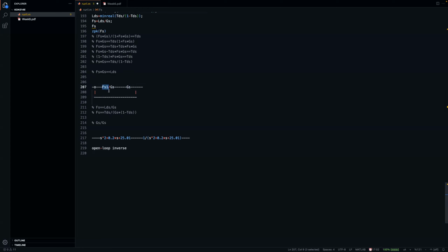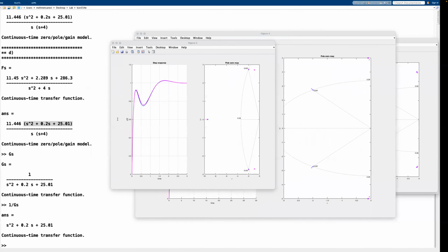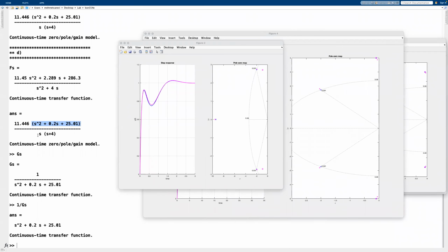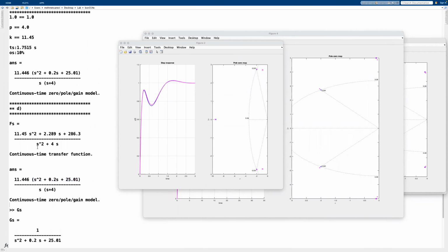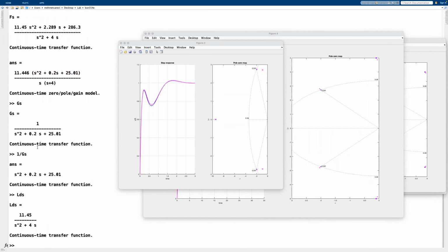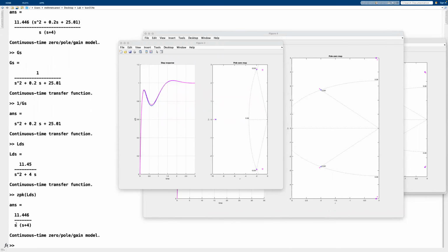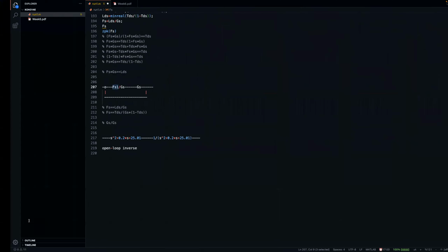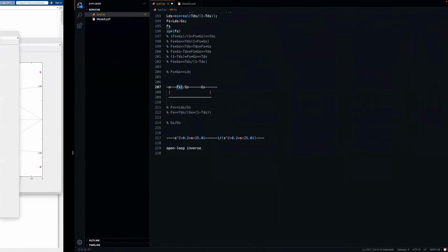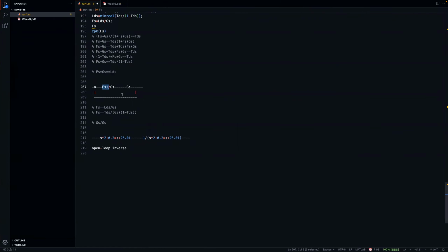And since we're measuring, you can also see that L(s) has an integrator on its own. So you can see zpk(L(s)). It does have an integrator at the origin, which increases the type of the system, because you need open loop pure integrators or poles at origins to track references for step, parabolic, etc. It pops up directly, so you can just assume that the model matching controller will always track references for step type inputs.